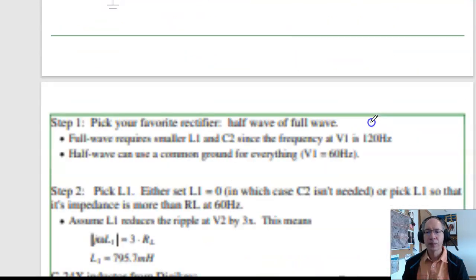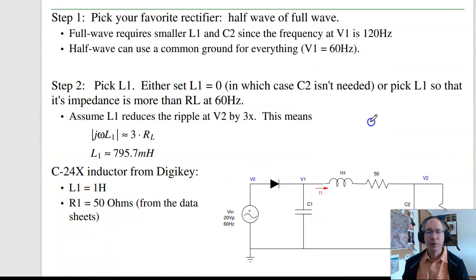Well, first you pick your favorite rectifier. I'm going to use a half-wave rectifier. Full-wave rectifier gives you twice the frequency. You can use a smaller inductor, smaller capacitor, but I need 4 diodes.